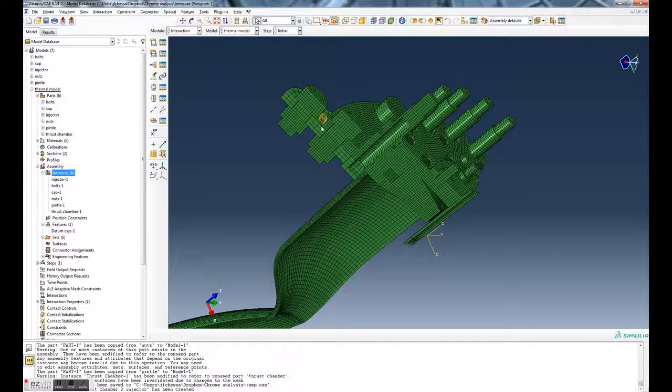All right. Now you can see it's going to be difficult to select the contact surfaces in the assembly because they're being blocked by other parts. So one of the things we'll have to do is isolate the surfaces to make it easier to select. This is probably the one thing you really want to pay close attention to. Defining the surface is relatively easy. Okay, so first I'm going to create the interaction.